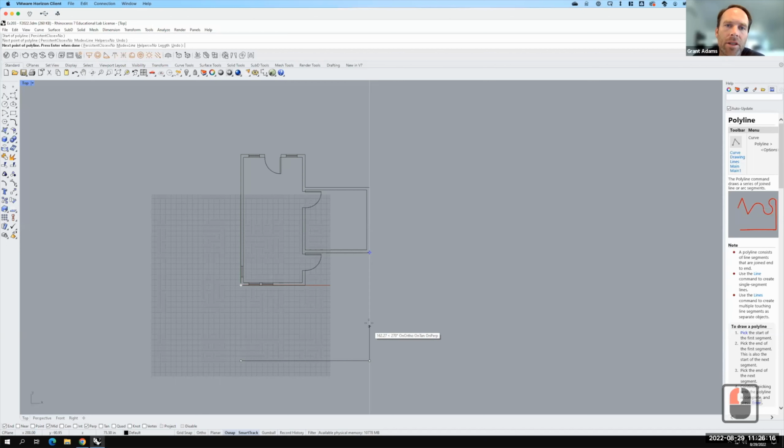Now the height of this wall that I'm going to create, we're just going to do a basic 8 feet. So I'll go up by 8 feet. And then I'll come over, and again, I'm using reference points here, so I can come over at perpendicular, and I'll come down to right there. That gives me the basic elevation view. I also need a line, and I'm going to use, again, those reference points. So I hover over that corner right there, get that line, pull straight down till I snap, and I'll snap again to perpendicular.